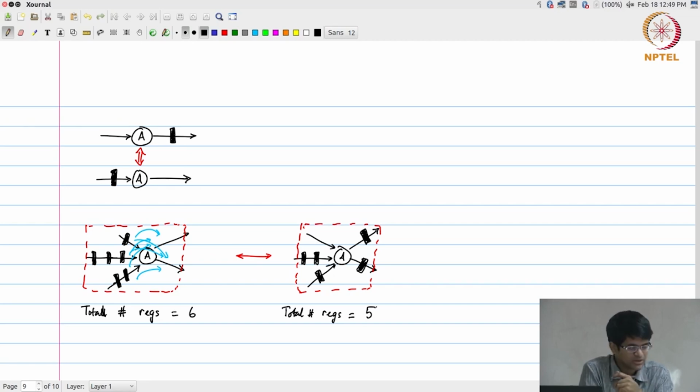reduction of area. So, in other words, the bottom line is this: retiming by itself is just a transformation. All that it says is, under what conditions are you allowed to move registers from input of a computational node to the output. If you do it completely on feed forward cut sets, it is a sort of simplified version that is called pipelining and is very commonly used. It can be applied in general for circuits that have feedback as well, provided that these conditions are satisfied, that anything going in one direction, if you are increasing the number of registers, in the opposite direction you need to decrease the number of registers. And at any point in time, the number of registers on a given edge cannot become negative.